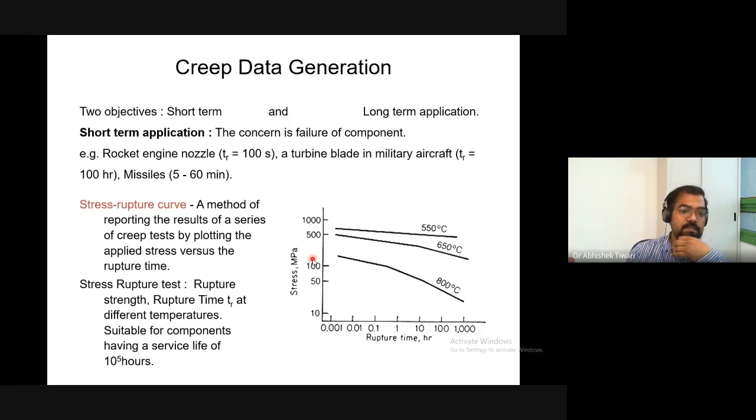So we have discussed the stress rupture test, where we load the specimen at a certain stress, and then we keep the specimen until it fails. If you plot rupture time versus different amounts of stress, then you may find a straight line, or you may find a change in the straight line with a slope, which describes a change in activation energy. So the mechanism is changing, and that's why the slope changes. This part also we have discussed.